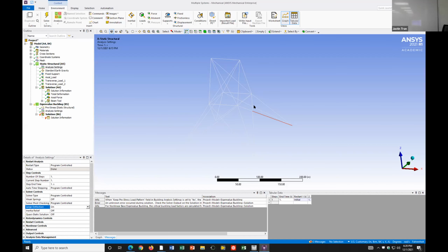But are these all black? Oh, so this multiplier is added to the total. It's added to all three of these at one time. Exactly. All the modes. So basically, if it's multiplied by almost 2.4, then we know that this leg right here, this piece, is going to fail. So these are a multiplier on the loads that you've already applied.